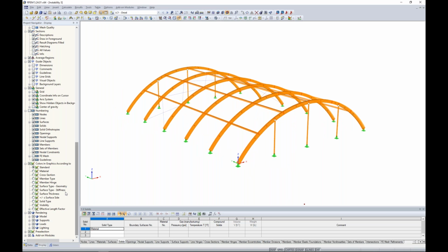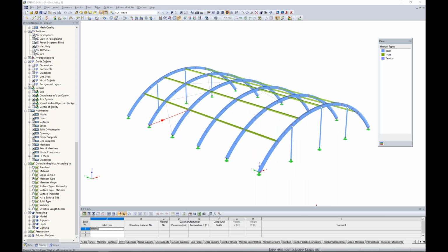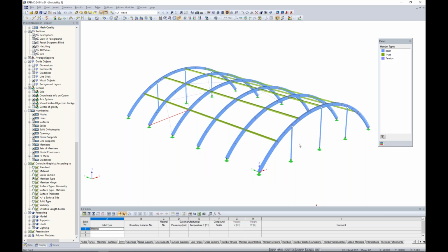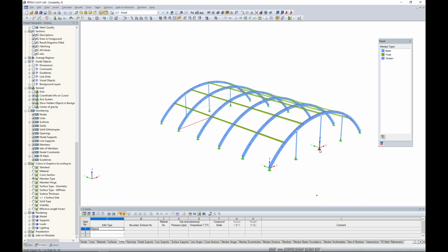But as we can see, typical glulam beam members here, and if I change my view here to the member type, I've defined truss elements in between these larger beams, and the truss just means that we're going to apply a moment end release at either end here. Then I have some tension only members defined here with my X bracing, and these are just going to be cable elements. Then of course at the front and rear of the structure, we just have these small columns defined here.